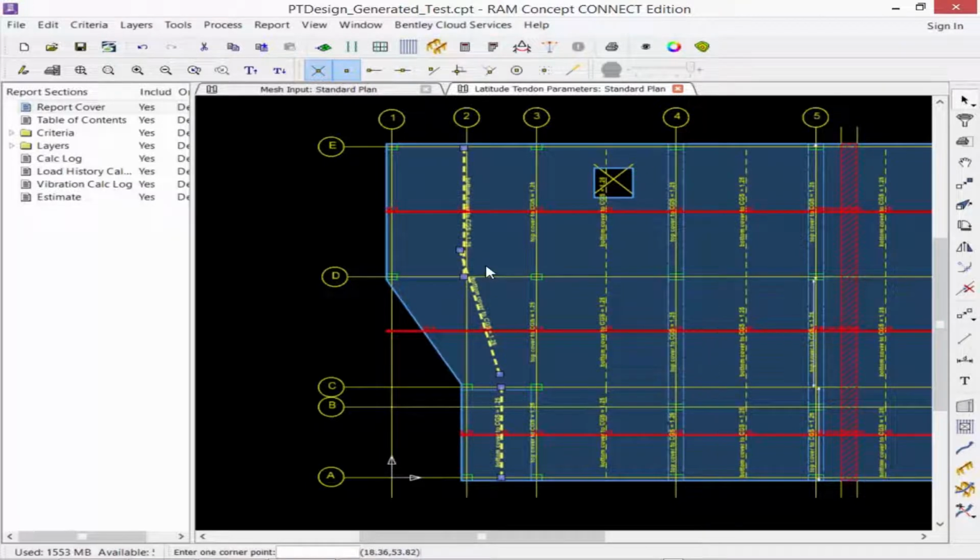Now, whenever a distributed polyline intersects one of these, either the support or span polylines, what's going to happen is it's going to take on that profile point. If you have one that's overlapping here, you may get two support points or two span points that are very close together. Here, you might completely miss that span point. So what we can do is we can use any of our manipulation tools to move, stretch, rotate, or mirror our span polylines. For this exercise, I have this one selected.